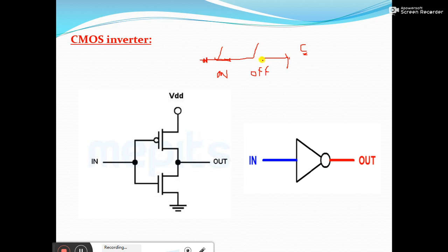So we have to look at whichever is not operating, whichever is zero, and predict from that. Let's say 5 ampere is flowing here. 5 ampere can flow through the on switch, but the same 5 ampere is broken down here. This is not a continuous path, so 5 ampere may come till here, but if you measure the current at this point, it will again be 0 only.